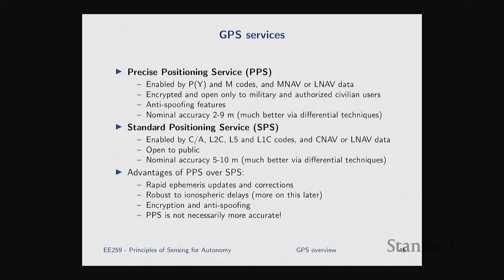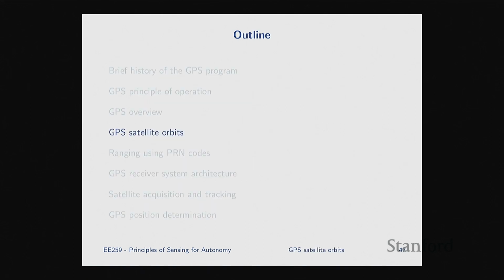But you still need much, much more accurate local measurements with other sensors to further narrow down your location inaccuracy from a few meters down to a few centimeters possibly, or even millimeters. It really depends on what the application is. But if you're in very tight spaces and your robot needs to navigate really intricate structures, you need much better than a few meters. So that's where this idea of sensor fusion becomes important, and that's why you need a variety of sensors. Each has its own unique capabilities, but ultimately you want to combine what you get from all these different sensors to get to what you need for your specific application. Okay, questions?